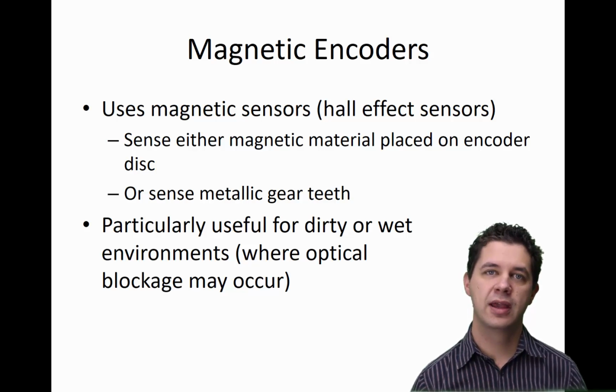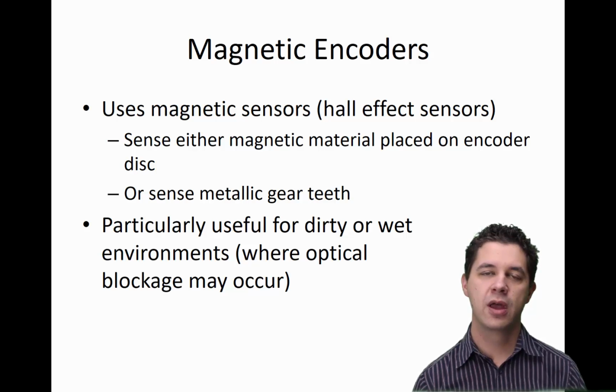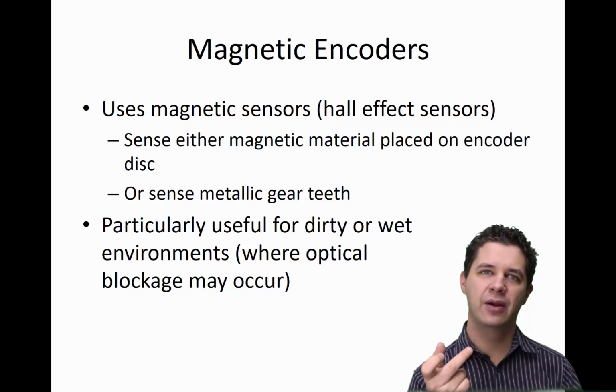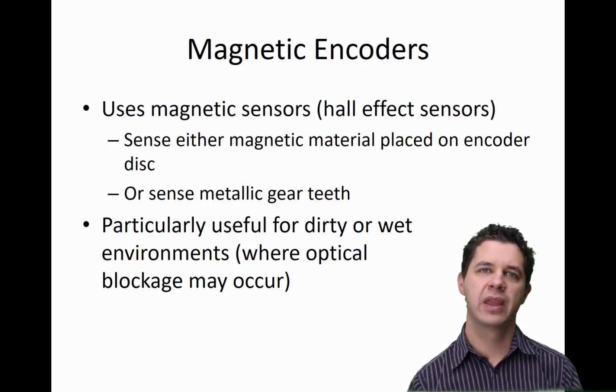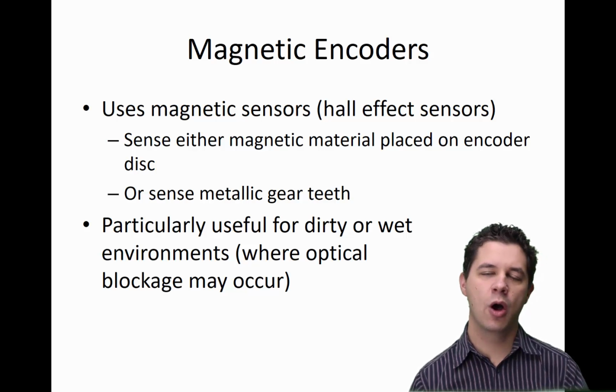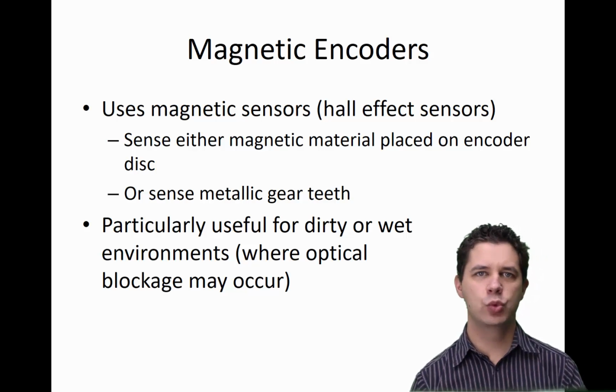Now the whole robot is rated at IP67, so it's waterproof, but the particular encoder needs to go on in the area of the robot that would be exposed. And if I used the optical encoders that we looked at earlier, it just wouldn't work.